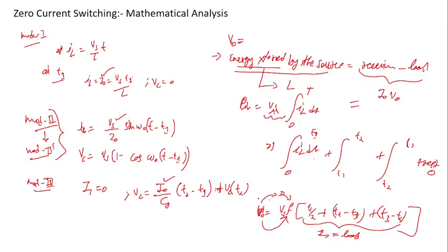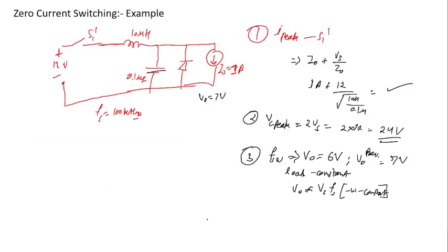I am talking about this equation, the output voltage equation, and this term depends only on the load, the input voltage and the inductance and capacitor. So the switching frequency depends on V0 prime divided by Vs prime multiplied by V0 divided by Vs, where the prime terms show the new values.